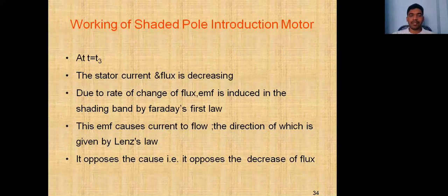Due to the rate of change of flux, EMF is induced in the shading band by Faraday's first law. This EMF causes current to flow, the direction of which is given by Lenz's law. It opposes the cause, that is, it opposes the decrease of flux.